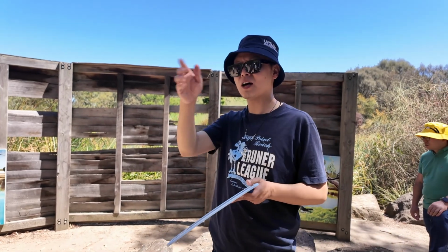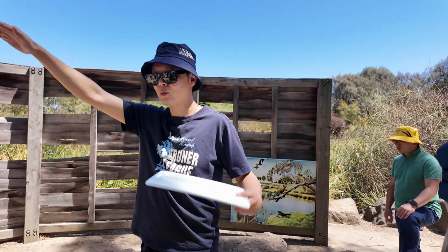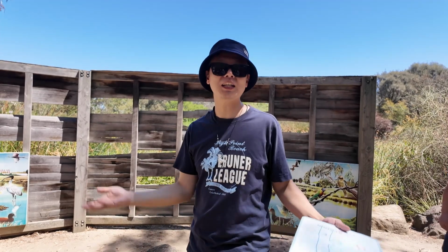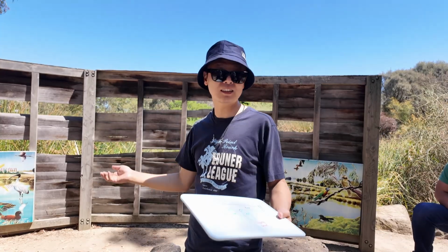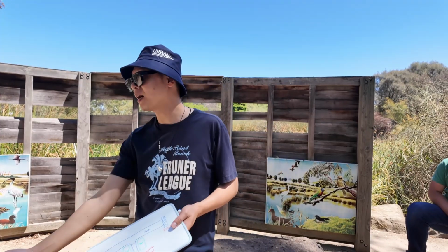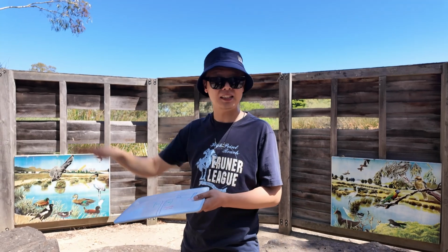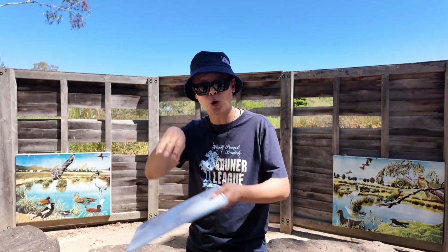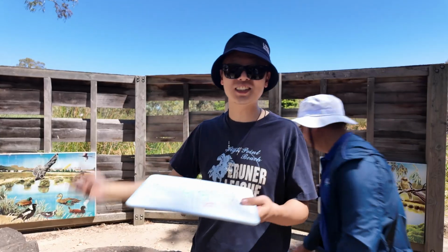I think Flo asked me this question, right? When you have enough vertical drop between the diversion and the wetland, you can have a submergible inlet. People think that's nice, but in Singapore, people actually like to see the inlet. So that's a cultural difference. There's nothing wrong or right with this. If people don't like to see the inlet, you just put a submergible pipe because there's enough height difference between the diversion and the actual wetland. In this case, it's about 2 meters. But in Singapore, when we design a project for them, they want you to showcase and expose the inlet so people see where the water comes from. That's two design concepts.